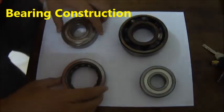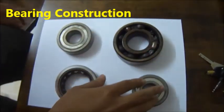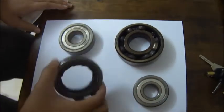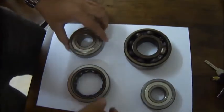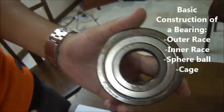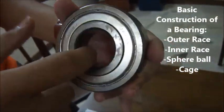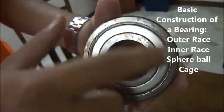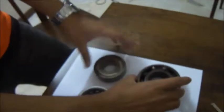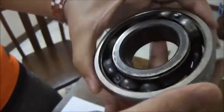Here we have an example of rolling bearings. This one is the single row deep groove ball bearing, and here is a cylindrical roller bearing. From this single row deep groove ball bearing, the outside is called the outer race, the inside diameter is called the inner race, and the cover here is called the cage. From this broken bearing, we can see inside the rolling element of the bearing, which is the spherical element, the ball bearing.